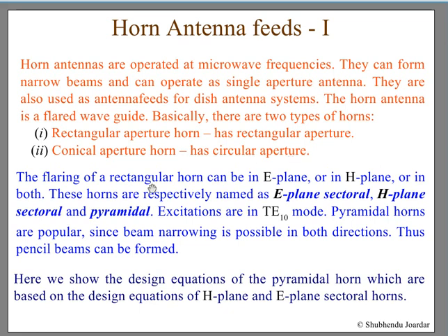The flaring of the rectangular horn can be in E-plane or in H-plane or in both. These horns are respectively named as E-plane sectoral, H-plane sectoral, and pyramidal. Well, I will show you all of this. And excitation is in TE10 mode. Probably you may be remembering what is TE and TM and TE10, TE11, and so on when you have been studying the modes of excitation of waveguides.